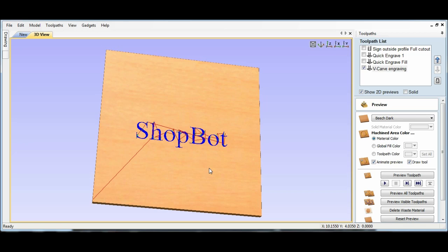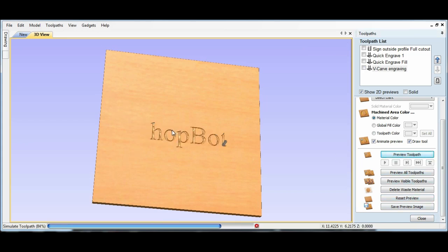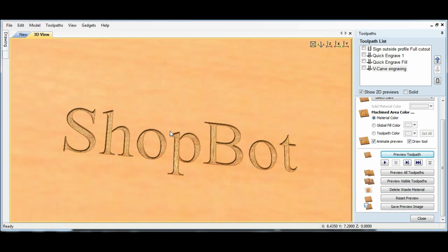Maybe that's a feature when it knows what you're trying to do. And since you're not, it knows that if it does its normal V groove depth, it's not going to hit the outside lines of your vector, so it automatically defaults to doing a fill pass. Now that could be complete BS, or it could be a feature that we just don't know. But in essence, all that did is now it did a quick engrave fill because it was too small. Yeah, it's very surprising.